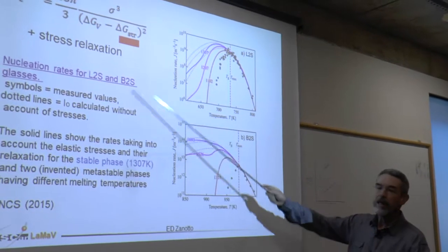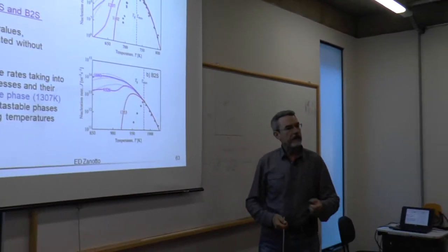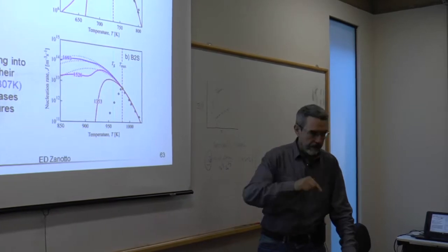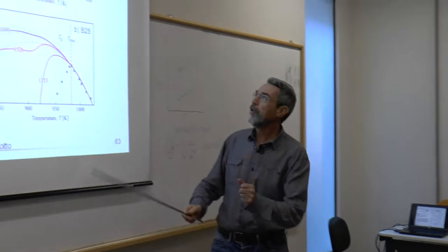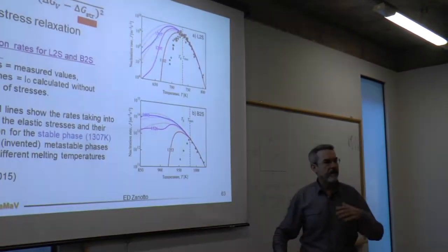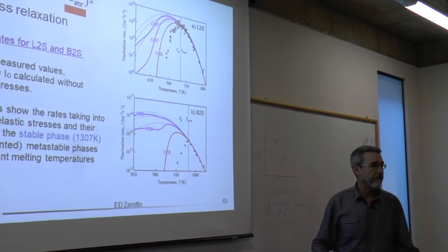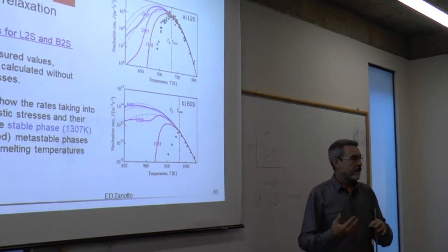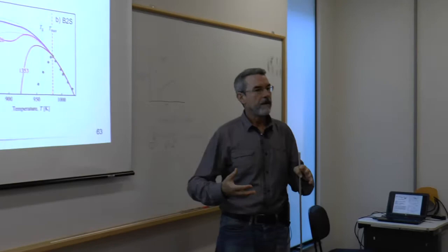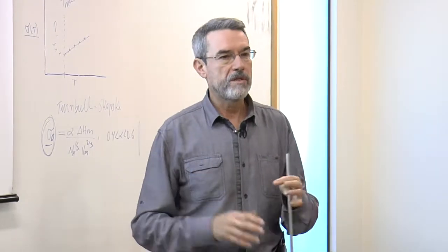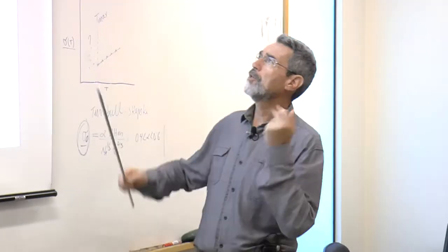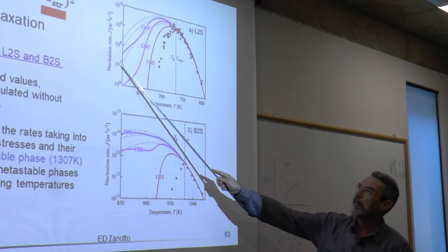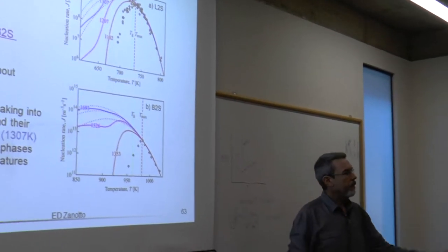And then we can retest the ability of the classical nucleation theory in predicting or describing crystal nucleation rate data in certain glasses, taking stresses into account. If we do that, let's take our Drosophila, lithium disilicate. Again, there's lots of data for lithium disilicate because it's a glass that the nucleation rates, growth rates, viscosity, thermodynamic data is all available. So that's why most people use this material as a model system to understand what's going on in crystallization. So, again, steady state nucleation rate in log, 10 to the power 6, 7, 8, 9, 10. This is the kind of range where we measure nucleation rates.